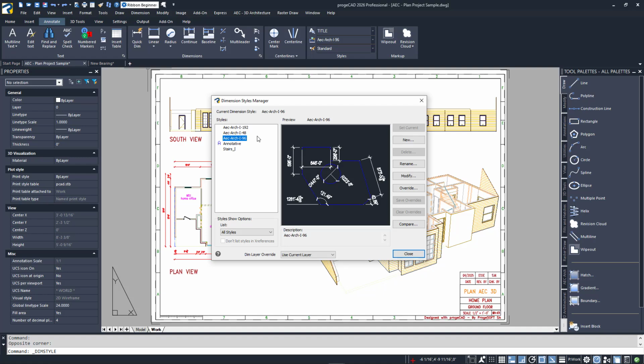There are numerous methods used to dimension drawings. One of the oldest and most commonly used methods employs styles as we see here, where the number represents the intended scale of the viewport that it will be displayed in. Dimensions are placed in model space with this method. The number is the inverse value of the scale.